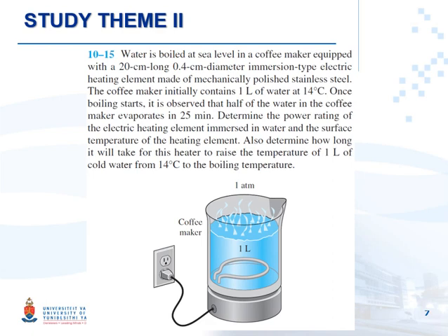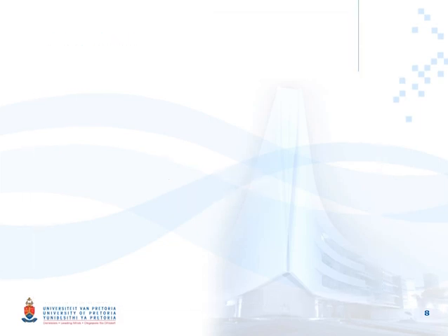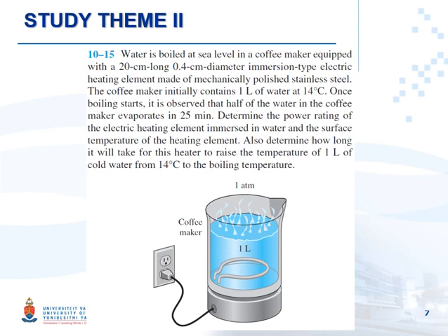So here is a little bit critical for us. Why is it critical? Because the question is asking us to determine the temperature of the heating element. When we don't have the temperature of the heating element on its surface, we can't really calculate the delta T excess to know what kind of boiling heat transfer or what kind of flow regime we are talking about. That's the situation that you might face during the exam as well. You might say, oh sir, I don't know anything about it because I can't calculate the delta T excess.